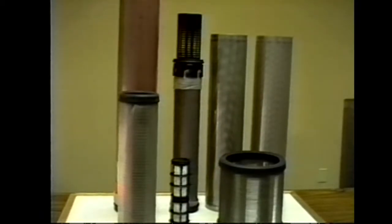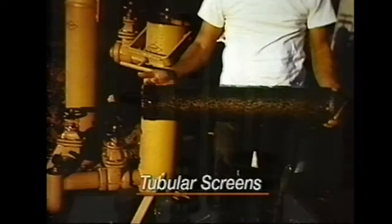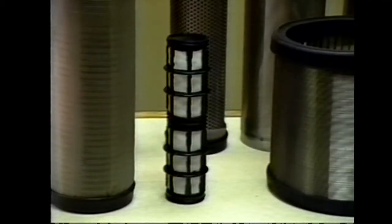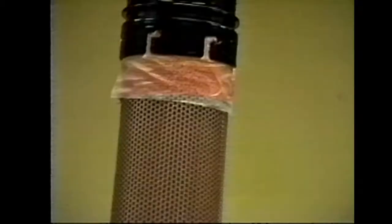Standard tubular screens are sometimes used with surface water as the primary filter. This is a serious mistake. Standard tubular screens are for extremely clean water situations only, such as downstream of the primary filter. They have only a two-dimensional cleaning surface and plug quickly if the water is dirty. There are major differences between tubular screens in terms of the direction of the flow, ease of cleaning, and construction.